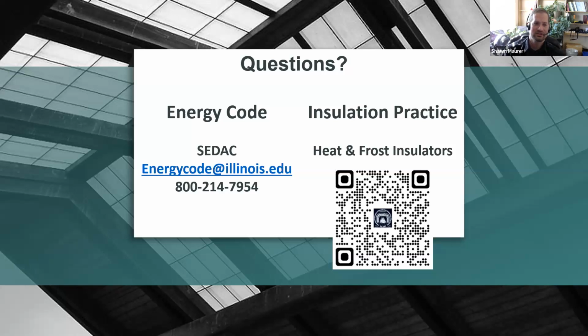But in this instance, looking at the elastomeric insulation, it will allow you to use that paintable coating, with the understanding that in the owner's manual for the building, there is the manufacturer's information on that coating that says this needs to be reapplied every 2 years as a maintenance practice. And the building owner needs to be aware of that for those systems. But it is a good point that is a maintenance practice that often gets overlooked.